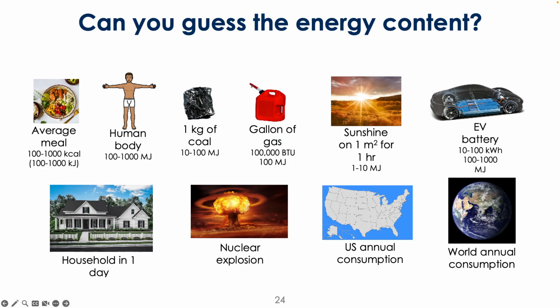Okay, how much energy does a house use in a day? Any ideas? Yeah. So the average power consumption most people cite is about 1 kilowatt, and then over a whole day, 24 hours, you're talking on the order of 20 to 30 kilowatt hours, right? So we're in the 10 to 100 kilowatt hour range.